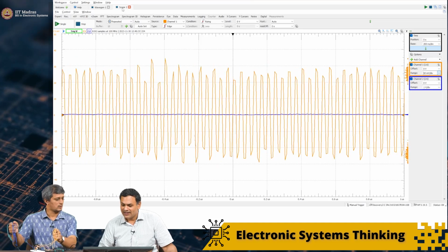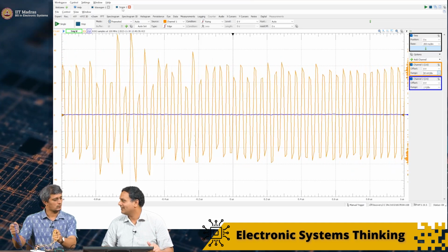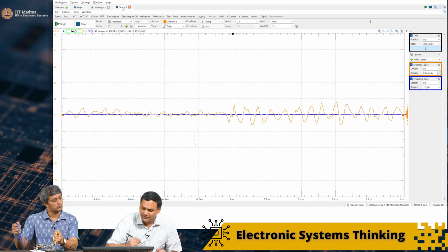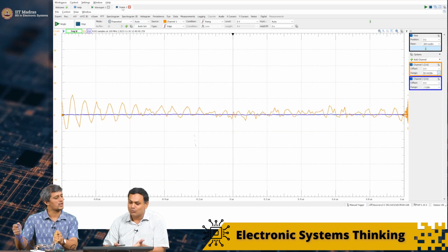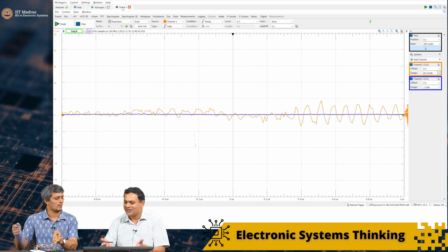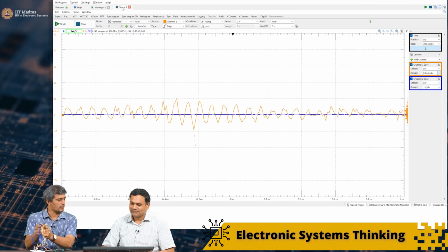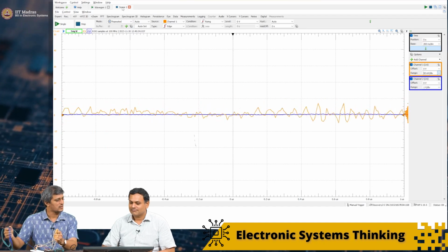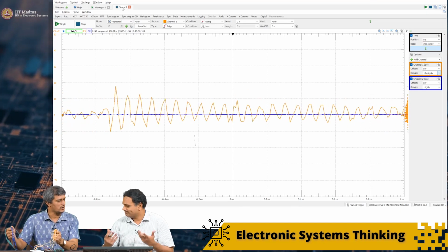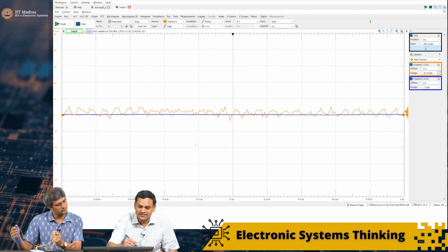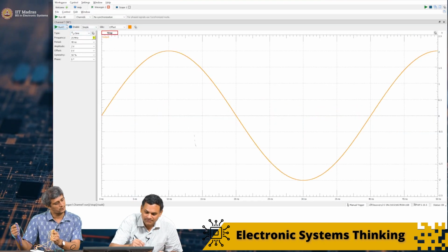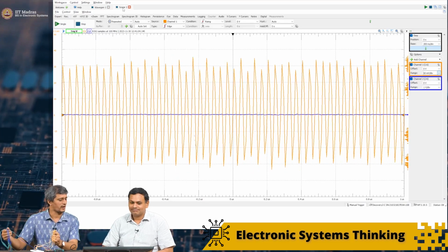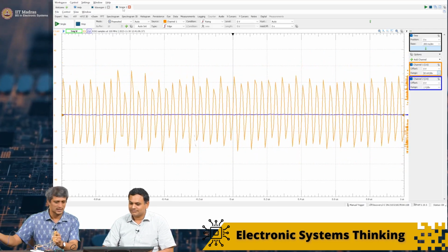In fact, what we can do is turn off the 25 megahertz and see what it gives. If I turn this off, you only get the noise, which is only a few millivolts. The intermittent noise that you are picking up. And if I bring it close, there's nothing. You keep it far away, it's still the same noise, and turn it on again. You can see the radiative component because it's sort of saturated.